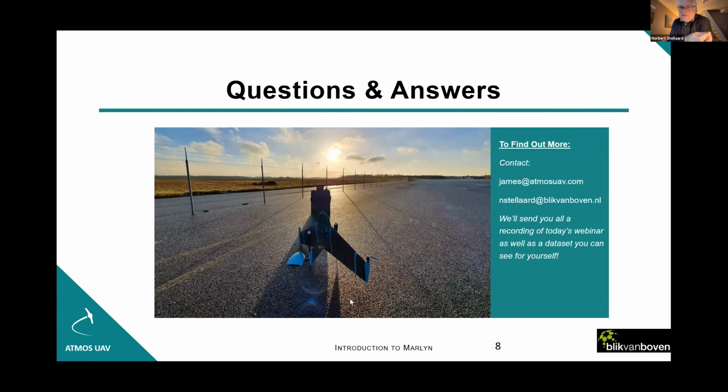If it's based on relative accuracy, then that's not necessary, because then the accuracy you need is only relative to the known object. So to summarize, for absolute accuracy, yes, you need to know the position of the base station. For relative accuracy, no, that's not necessary.